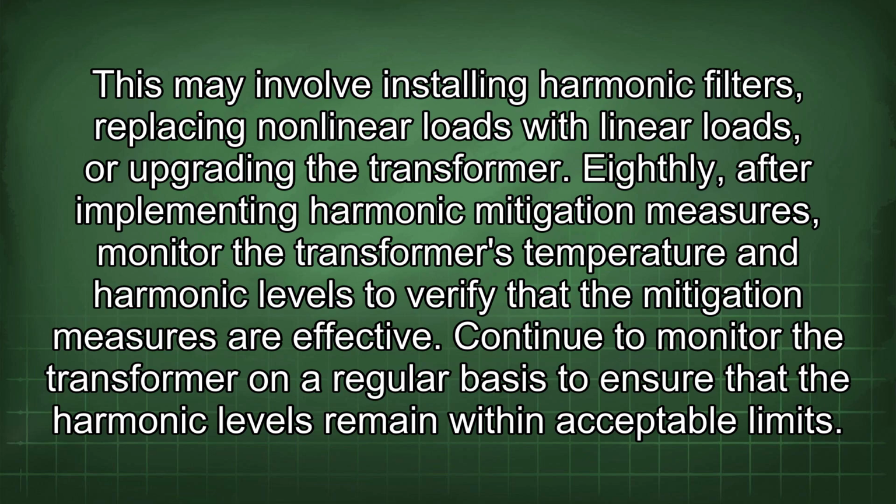Eighthly, after implementing harmonic mitigation measures, monitor the transformer's temperature and harmonic levels to verify that the mitigation measures are effective. Continue to monitor the transformer on a regular basis to ensure that the harmonic levels remain within acceptable limits.